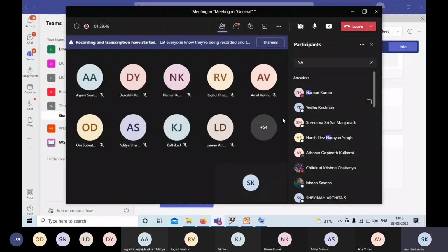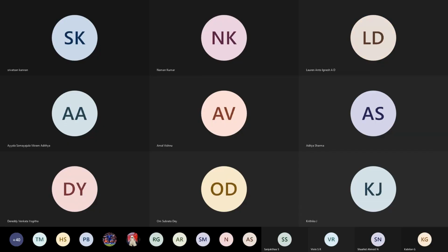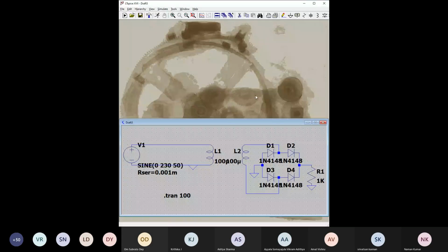You can show the circuit diagram now. Can you see it, sir? Four diodes, two resistors, two inductances. And what you have to set in the SPICE directive is K L1 L2 1, since you have only two inductances. Oh, yes, I have not done that.